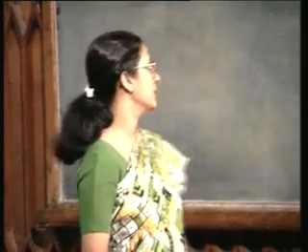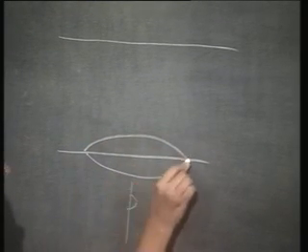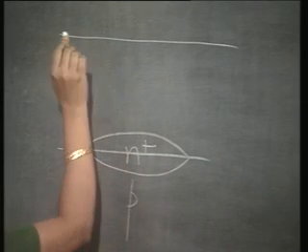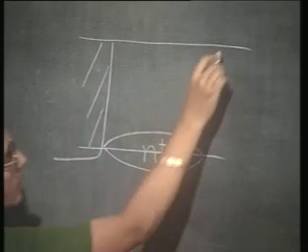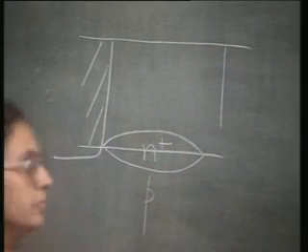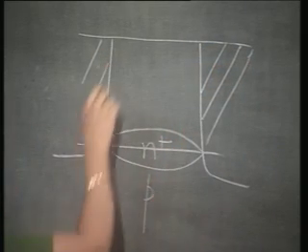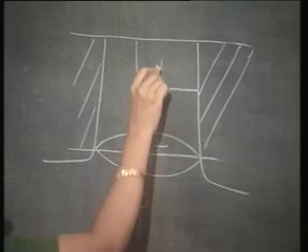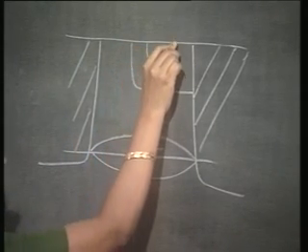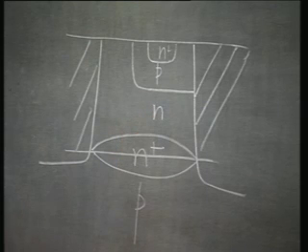Now, what do I mean by the active base? What I mean is simply this: I have this transistor, started from a p-type substrate, had the N plus buried layer, then I have the N epitaxial layer. I can have some kind of an isolation, either junction or oxide. Let us say I have oxide isolation here. And then I have the P base region, and then I have the emitter. So, this N plus P n is actually my transistor, right.